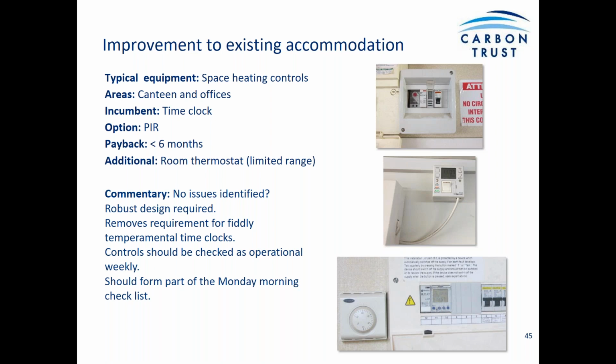The good thing is that it does remove that requirement for the time clocks, which are often very difficult to work out how to program, and things go wrong with them and they can't be fixed. So the guys on site then just have to bypass it, and it's usually left on then. As a result, again, would encourage that these kind of controls are checked on a regular basis.